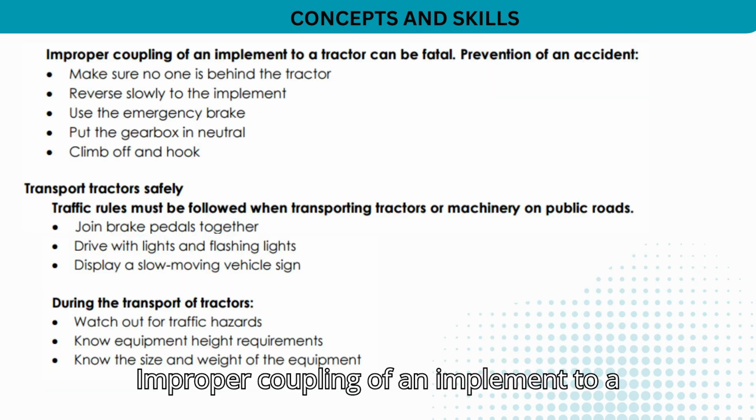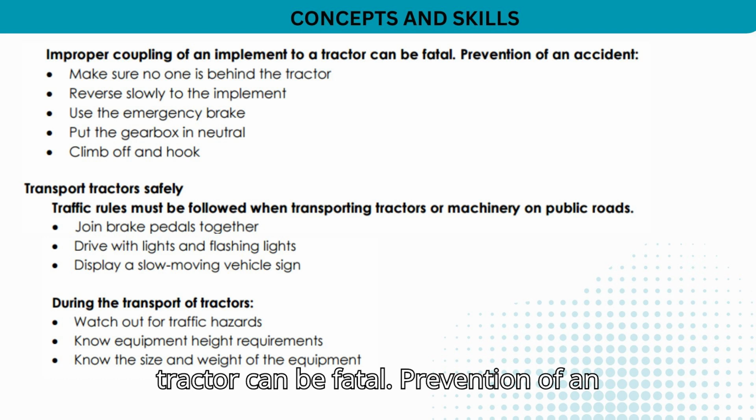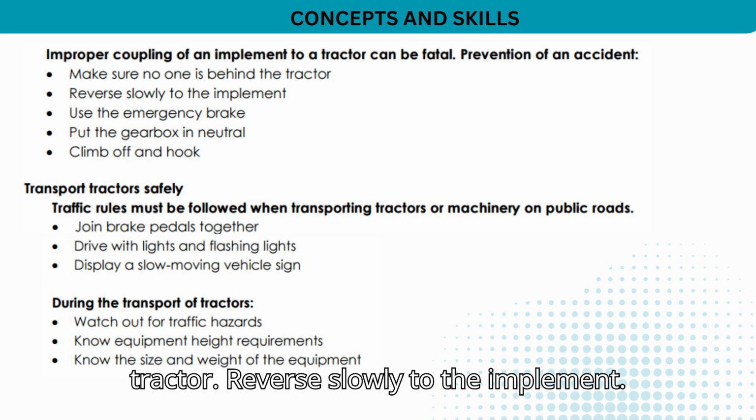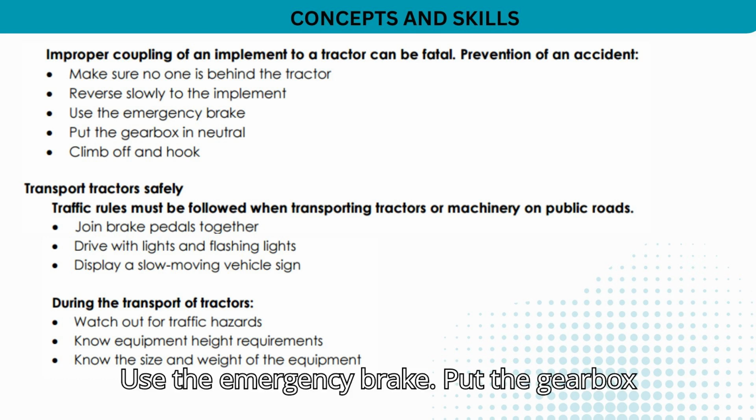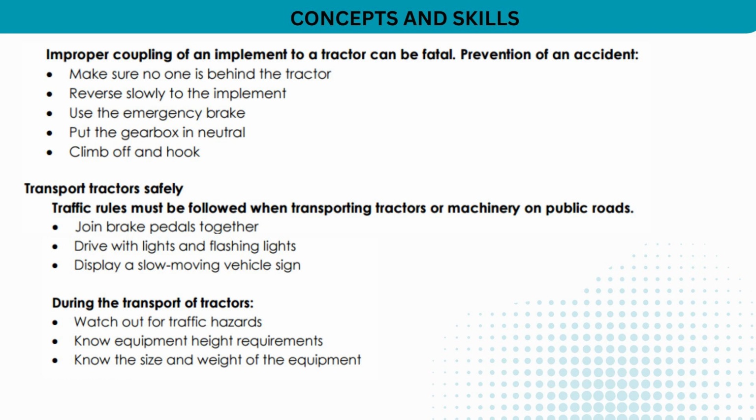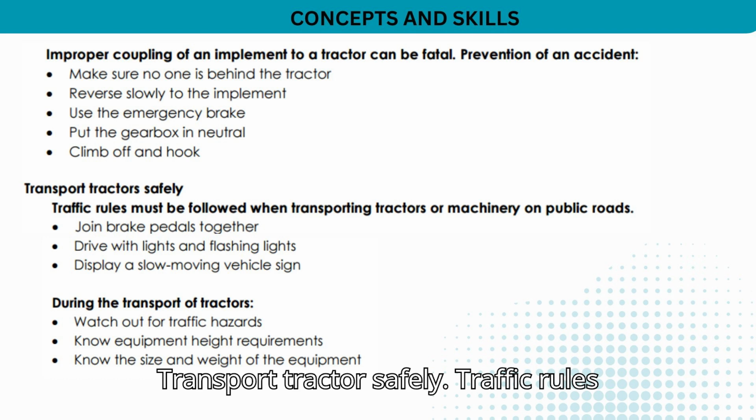Improper coupling of an implement to a tractor can be fatal. Prevention of an accident. Make sure no one is behind the tractor. Reverse slowly to the implement. Use the emergency brake. Put the gearbox in neutral. Climb off and hook up.